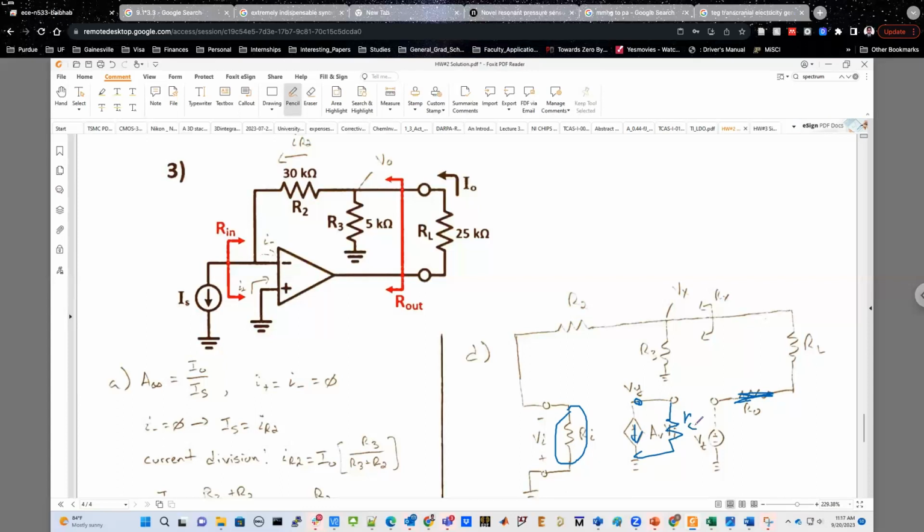Because if you don't do this, the Thevenin and Norton equivalence will not be there. You know from the Thevenin and Norton equivalence that you can represent any voltage source as a voltage source in series with a resistance. That can be considered as an equivalent current source with a resistance in parallel. So if you are considering this as a current source, consider this resistance in parallel, not in series. And then do the same calculations.